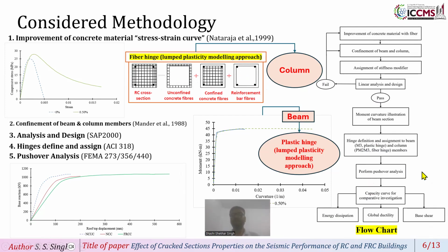After that, we do the analysis, and we will get the capacity curve for comparative investigation. Finally, we are getting energy dissipation, global ductility, and base shear. This is the complete flow chart.